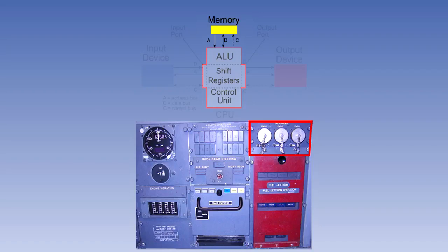This is achieved on a 28-day cycle when a company, such as Jeppesen, contracted by the airline, issues an updated software program. This program is loaded into the FMS by a technician, overwriting the old data in the EAROM with the new.